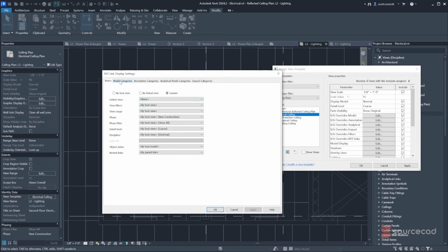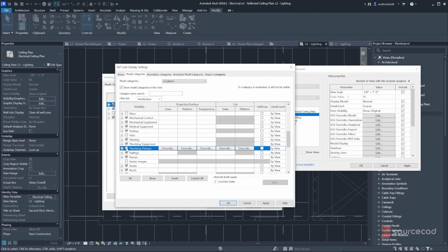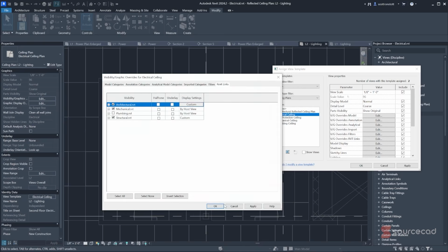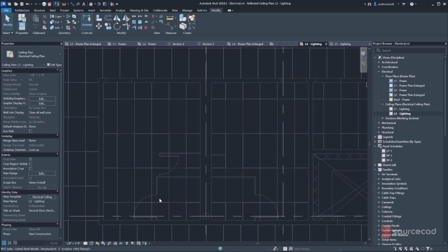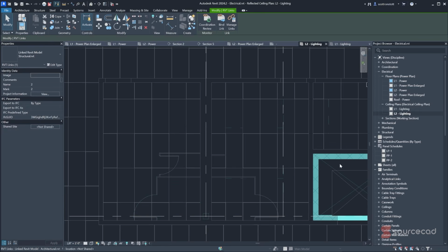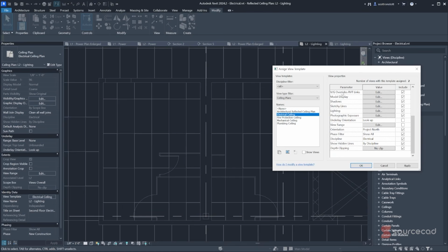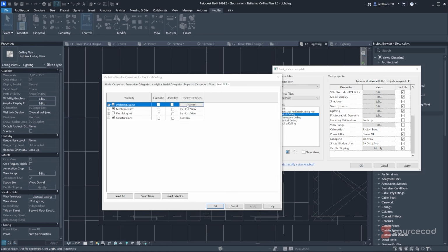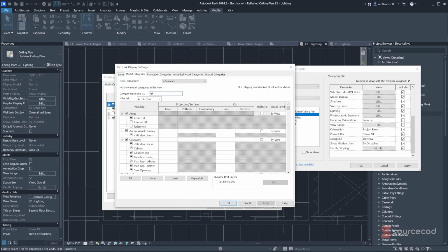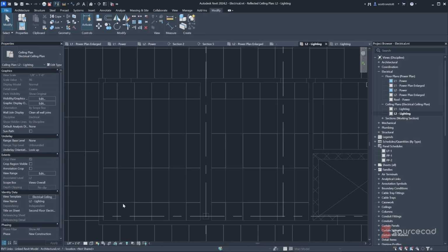So we're going to have to customize how that's shown. And in particular, I want to hide anything having to do with plumbing fixtures or plumbing equipment here. We got rid of the urinal, all right. This is part of the architectural model, and if I tab, I can actually click on that and see what it is. This is specialty equipment. Okay, so I learned that, and now I can go back into my template and edit the architectural link and get rid of specialty equipment from the architect. There we go. This is suitable finally for a lighting plan.